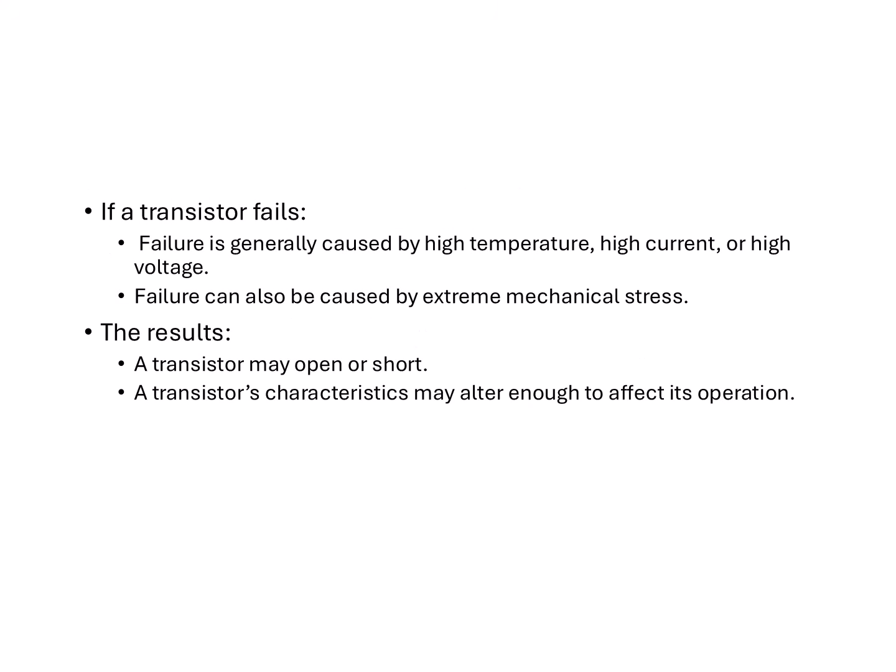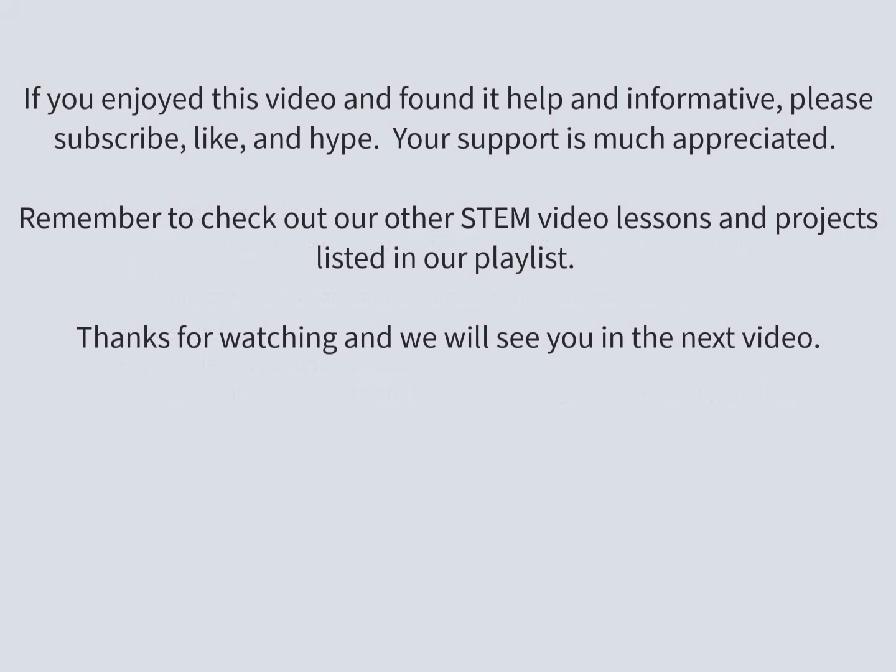A transistor may sometimes fail. To see if a transistor has failed, check for physical signs like burns or use a multimeter set to diode mode. Test the junctions between the base, collector, and emitter. A good transistor acts like working diodes, showing a voltage drop one way and open circuit the reverse way, while a failed one shows a dead short or open circuit everywhere.